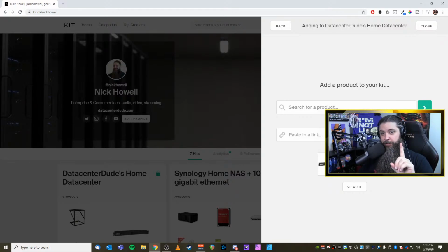You should have one of those, if not 2 of those per rack. If you want redundant power, if you have redundant power on anything, you want to split your power from your device to 2 different ones of those. Don't plug 2 things into the same PDU, please. It's pointless. So we got shelves, we got that.